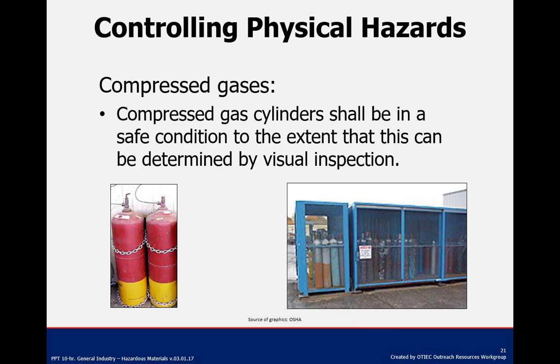A cylinder should always carry a legible label or stencil identifying the contents. Do not deface or remove any markings, labels, decals, tags, or stencil marks used for identification of cylinders' contents. Empty cylinders and cylinder storage areas should be clearly marked with appropriate labels and signs. Assigned storage space should still be located where cylinders will not be damaged by passing or falling objects or subject to tampering by unauthorized persons.